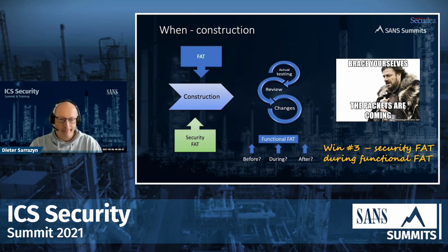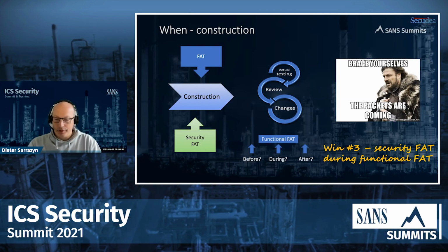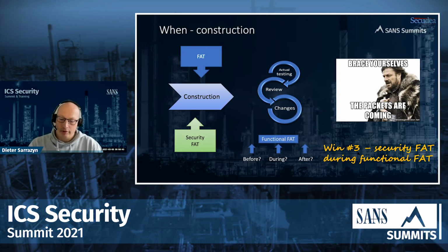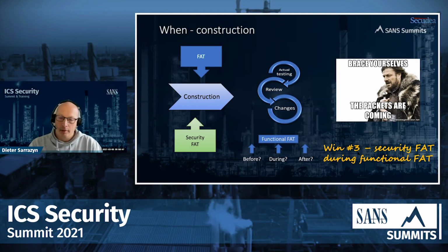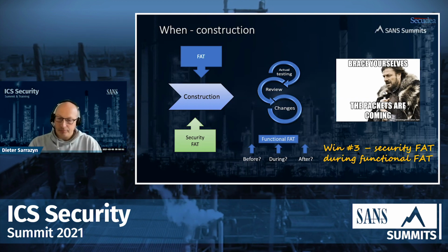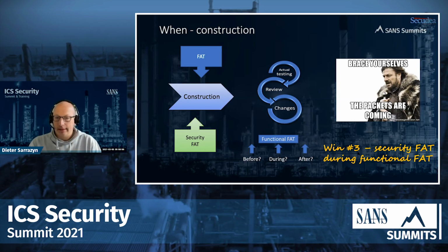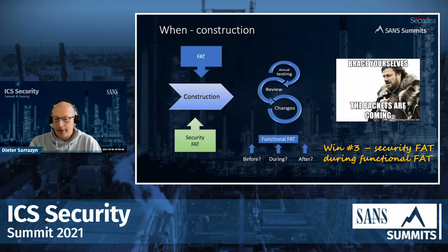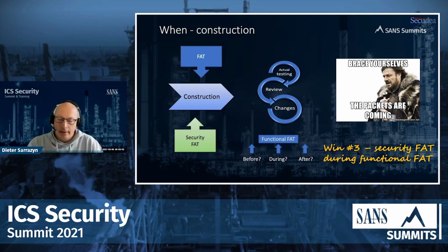Oh, okay. That's something good to keep in mind, because of course, during the SAT, you should not retest that particular PLC anymore because it's already in an almost productional environment. But it's very important to know for the overall availability state of that system, because if that PLC fails by just doing a port scan, well, that's a red flag actually.